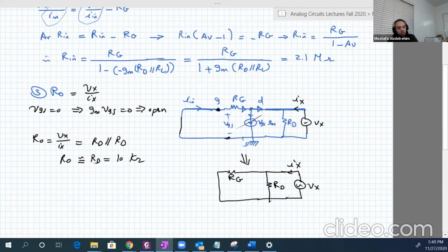Okay, guys, so this is basically the common source amplifier. It has moderate to low amplification gain. It has very good input resistance. It has moderate to high output resistance. It beats common emitter, if we compare it, because it's analogous to common emitter, in the R input. Same R output, but it has less, we can say, but we can manage that.